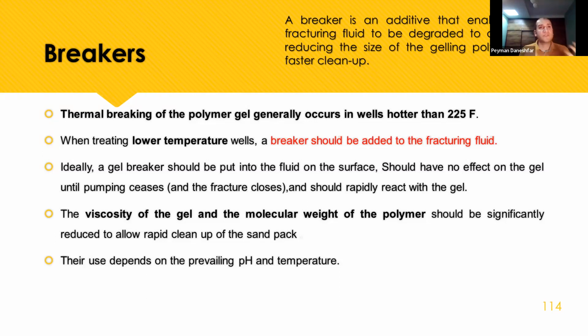The viscosity of the gel and the weight of the polymer should be significantly reduced to allow rapid cleanup of the sand pack. Their use depends on the prevailing pH and temperature.